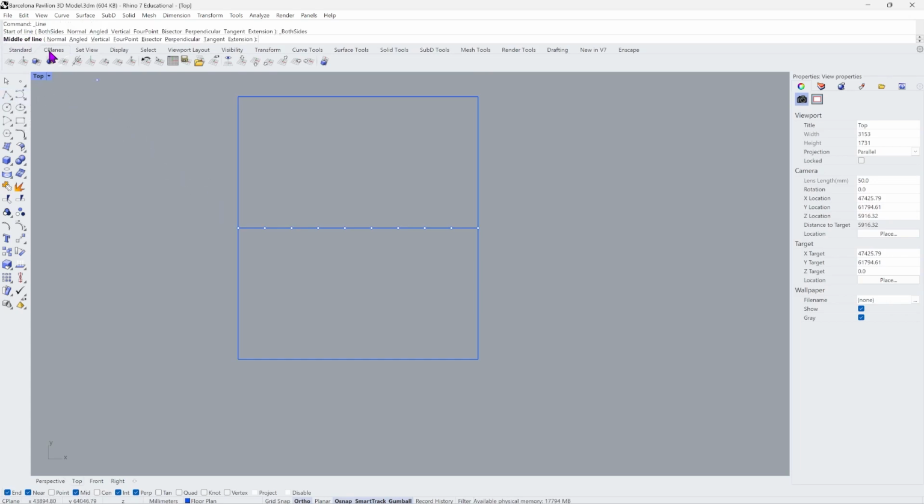In this way, I can choose a middle of a line, which I know is going to be this point in here. Make sure that you need to be able to snap to the point. So make sure that when you go to all snaps, you choose point. And now you can snap to this point, click once, make sure that your snaps are on, your ortho is on, and you can start drawing a line that goes from the top to bottom from the middle point. Click enter again. You don't need to retype the same command again. Make sure that your curves are nice and vertical, parallel to each other, otherwise we're going to have wonky stairs. And we continue drawing our steps from the midpoint.